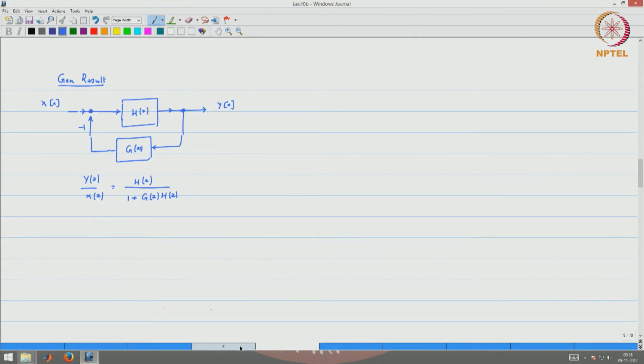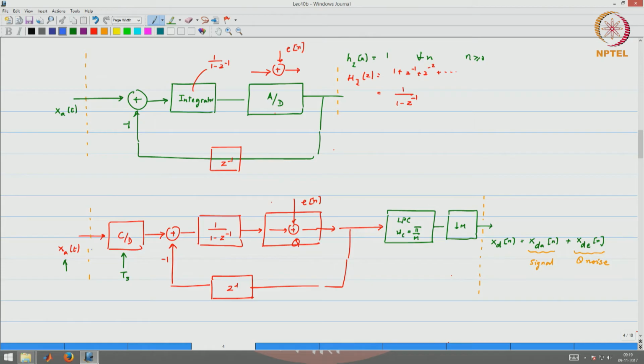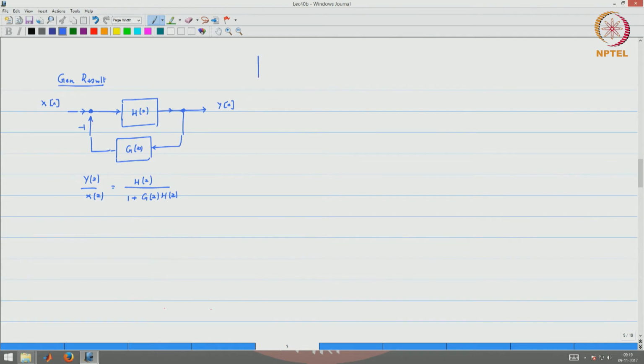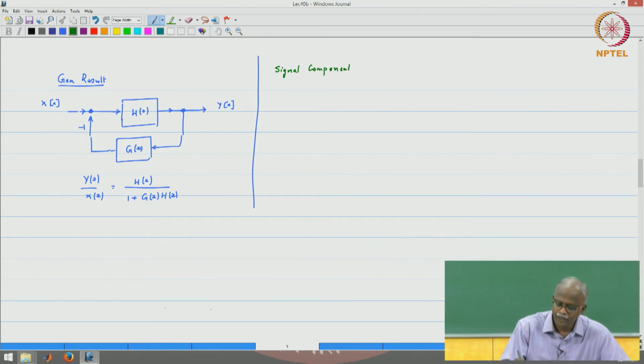So, now go back to this figure and find the transfer function between the input signal, okay, let this be the point we are interested in, x[n], to the output y[n]. Okay, we have not done the downsampling, we have not done the filtering post, basically just this portion of the transfer function. Okay, so for the signal component, please keep the diagram as your reference and verify that the forward transfer function H1(z) is given by 1 over 1 minus z inverse.